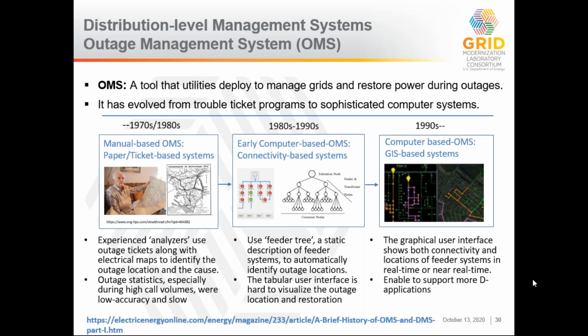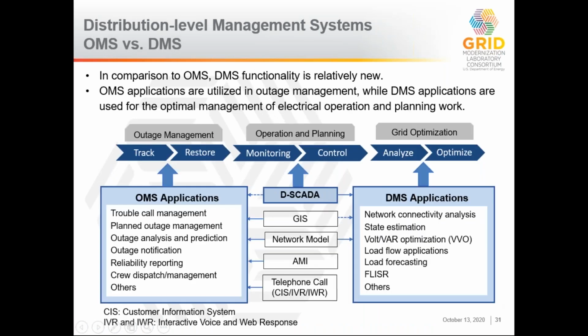So next slide. The next stage that people talk about is the distribution management system functionality, which is not necessarily the outage management system, which is generally where you're looking for the trouble parts of the system. DMS is where you're actually trying to manage the system in its operational state where it's working well. It's how we put in new types of applications. It can improve the outage management system in that it can implement various tools that will probably reduce the number of outages that you have and help locate things faster. But it's not the outage management system.